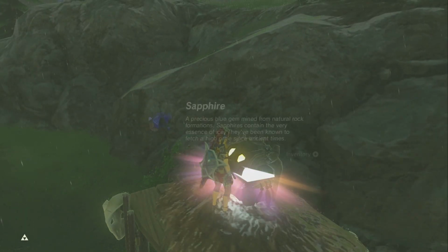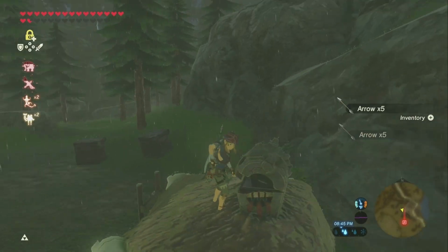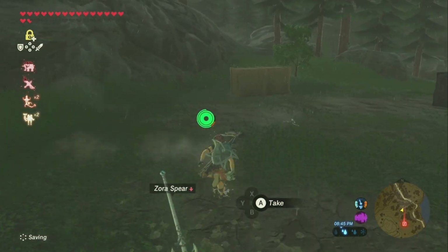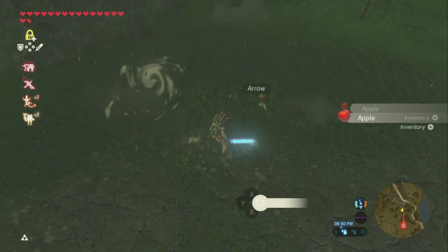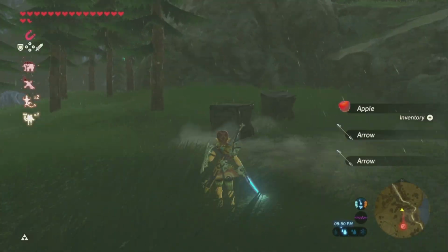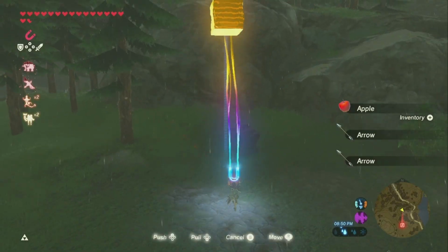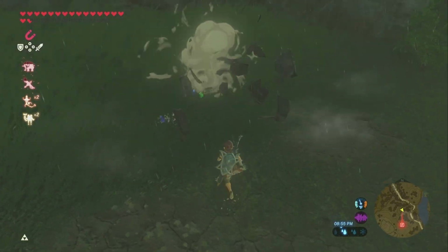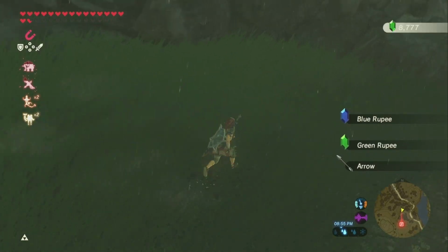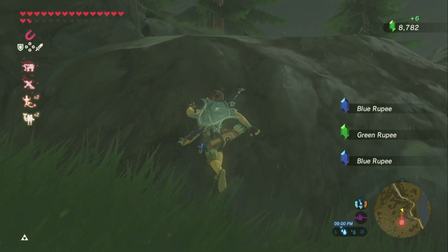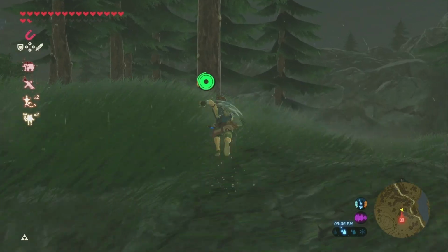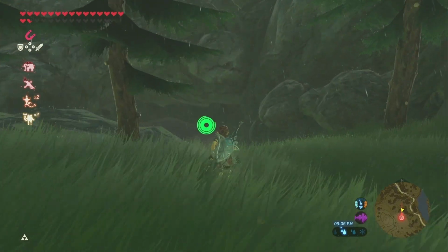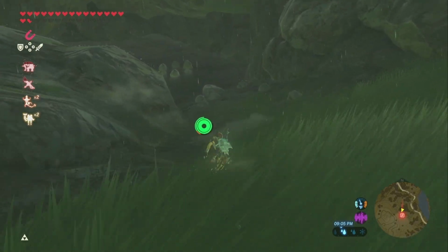There are few inspection issues with respect to dual water heaters. Ensure each heater has its own shut-off valve. If they are gas-fired heaters, they should have individual gas shut-off valves as well. Most importantly, both heaters should have independent TPR valves with independent discharge pipes, which should never be tied together. This is a safety issue.